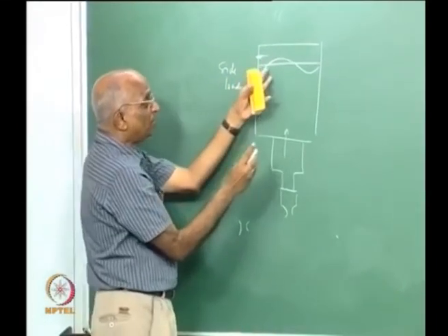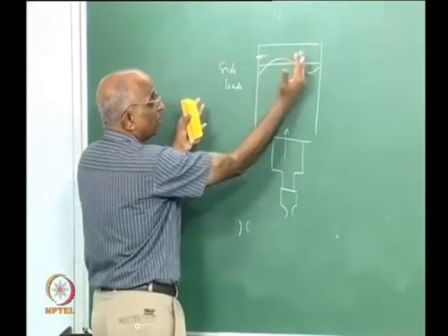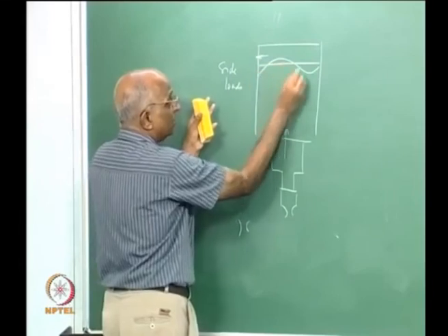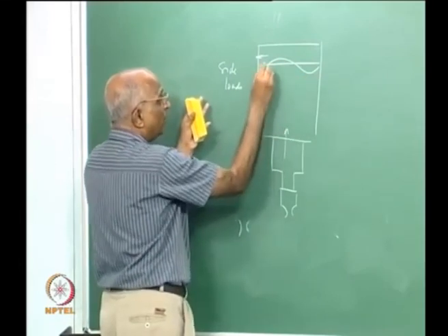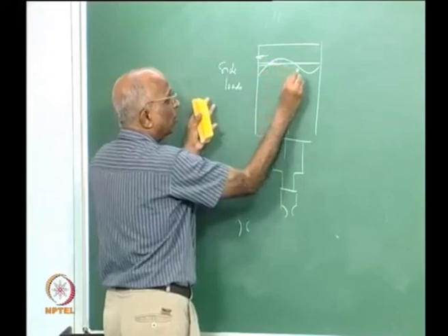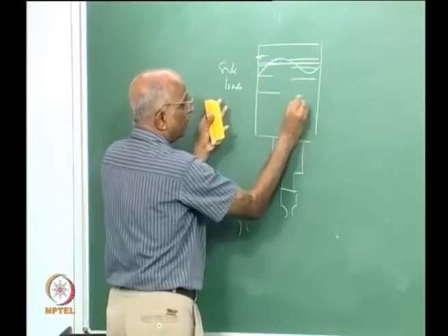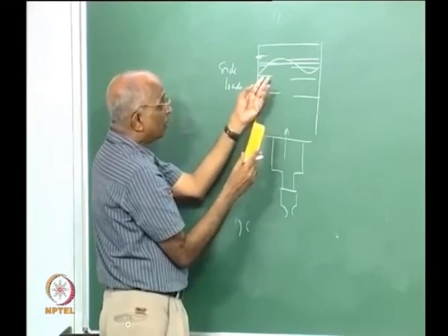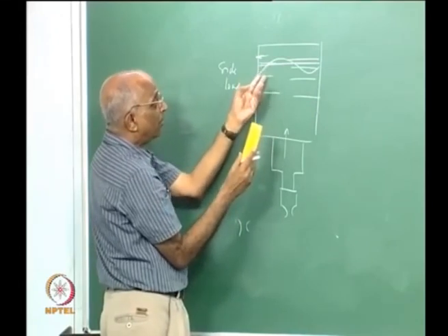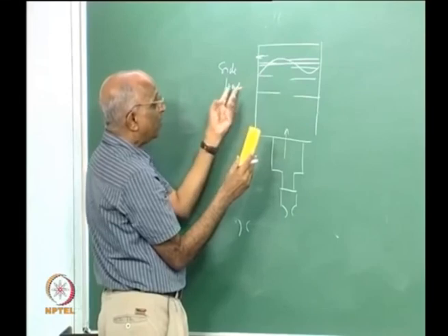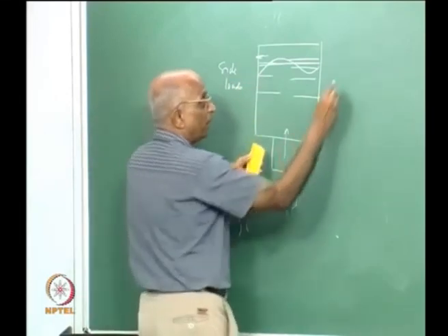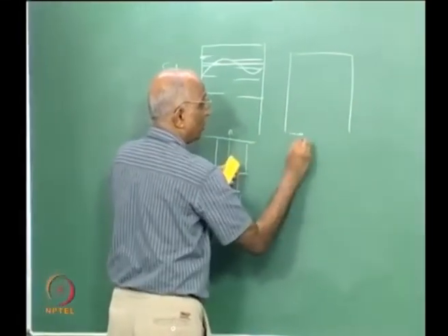And therefore, what do we do? We start getting side loads because the propellant sloshes, that is, the free surface of the propellant changes. Therefore it becomes necessary to put something like baffles, which, because of viscous dissipation, will not allow this to happen, and so I put baffles in my propellant tank to avoid sloshing.